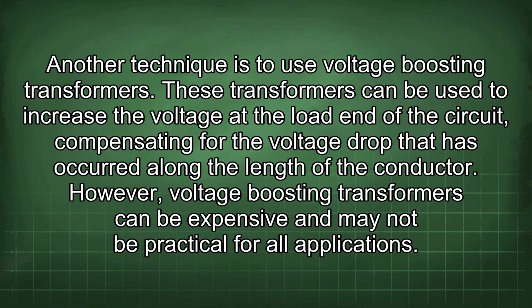Another technique is to use voltage boosting transformers. These transformers can be used to increase the voltage at the load end of the circuit, compensating for the voltage drop that has occurred along the length of the conductor. However, voltage boosting transformers can be expensive and may not be practical for all applications.